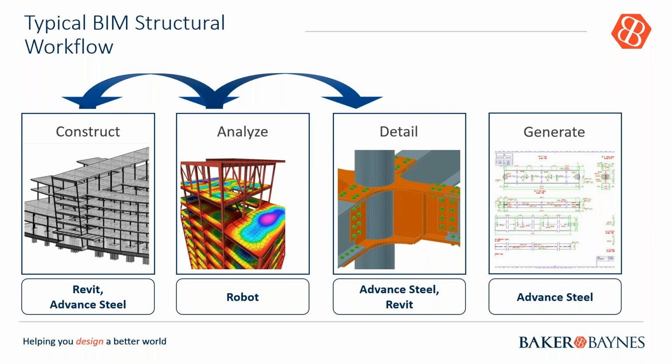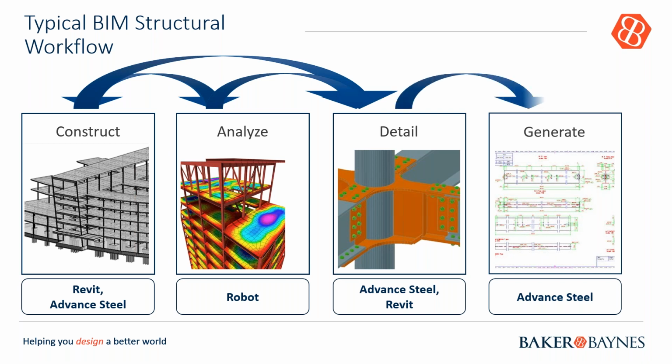If you're doing rebar, you can do it in Revit Structure, which is amazing with automated sections and 3D views. And then of course, the detailing of the finer elements, as you can see in the graphic. You can also jump directly from Revit to Advanced Steel, if you do not want to do the analysis part of it. And once you detail it, you can generate your shop drawings and so forth. It literally looks like this. You can customize the colors, but if you're like me and want to use something out of the box, it looks pretty decent. So please give it a shot.